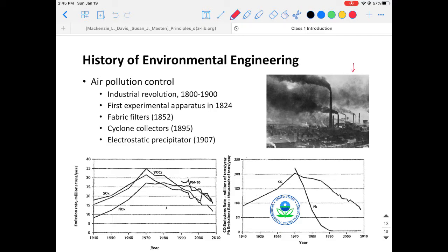I'm not sure if you guys have visited or have driven past certain power plants. What we can normally see is that the smoke coming from the stack is normally white. It looks white mainly because there is a lot of water in there, and it's maintained at a high temperature in the flue gas. So by having a lot of water, the water vapor is going to condense. So basically we're forming small clouds there. That's the reason why it looks white.